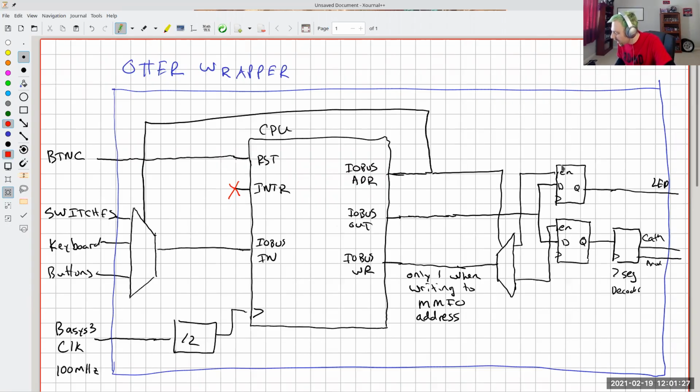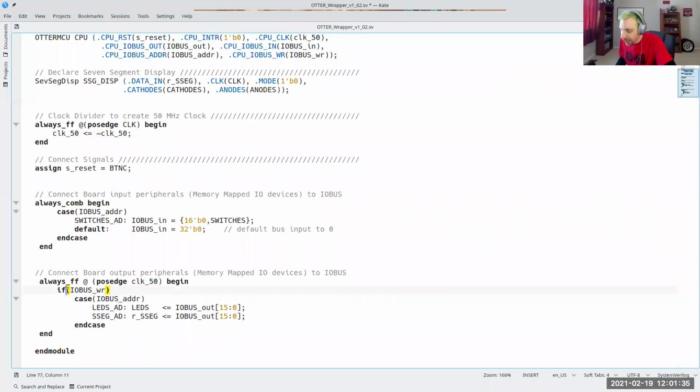So I'm essentially updating those registers. And so this whole thing sort of gets all combined into one block, right? If I look at actually what I have here, the first thing I look for is what? Make sure you're only writing when the enable is high.